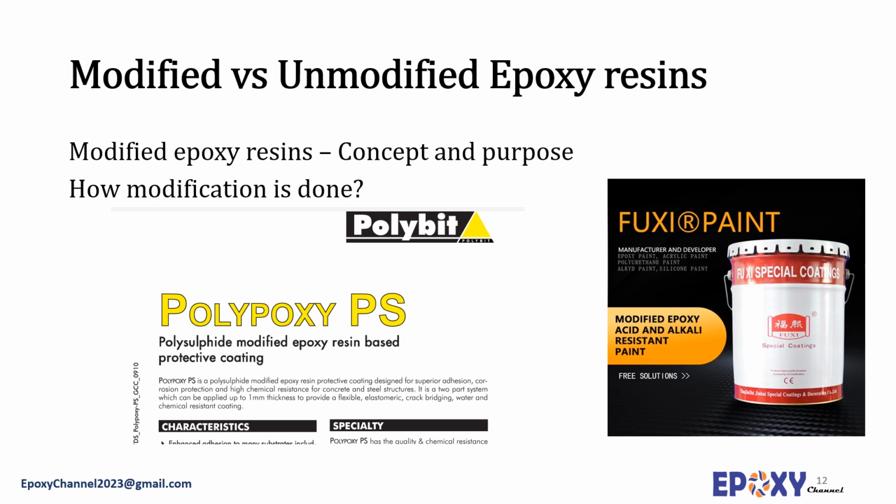There are hundreds of ways that the formulation can be modified: by adding mineral fillers, talc, silica, aluminum, etc.; by adding flexibilizers, viscosity reducers, colorants, pigments, thickeners, accelerators, adhesion promoters, etc. These modifications are made to reduce cost, to improve performance, and to improve processing convenience. As a result, a typical formulator sells various formulations, each tailored to the requirements of a particular application or market.